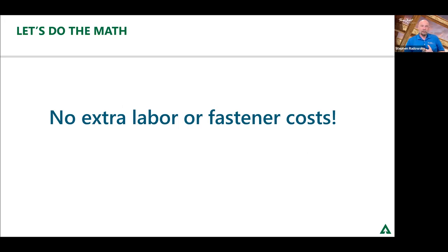You may, but if you look at any manufacturer, whether it's us or a competitor, even if you are plying the materials together from an LVL, the understanding is that those LVLs will be supported in such a fashion that they stay straight and true during the application process. So for those of you that are carrying them up your scaffolding, setting a ridge board into place and then nailing the second, third, or fourth together, I really hope that you have some type of support so that you're not inflicting self-weighted deflection and then adding your roof rafters and wondering why your roof has a fantastic Asian flair to it with that sloped roof.